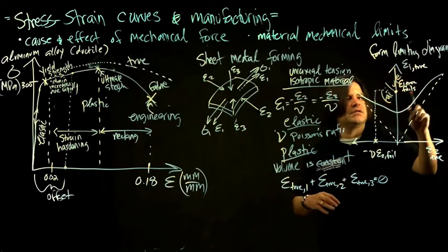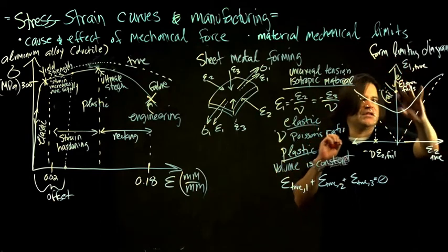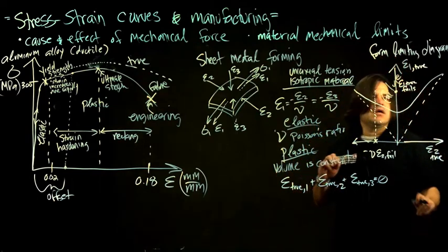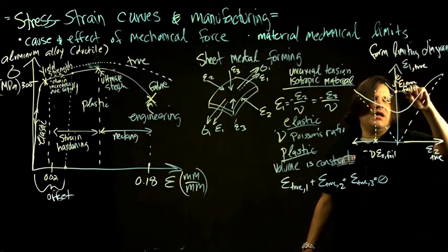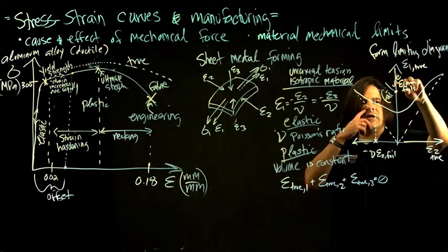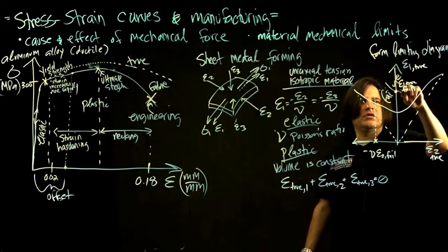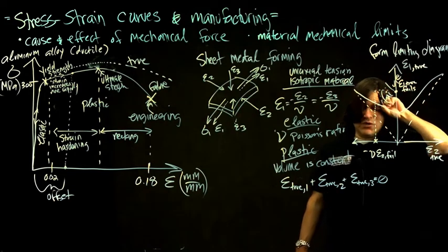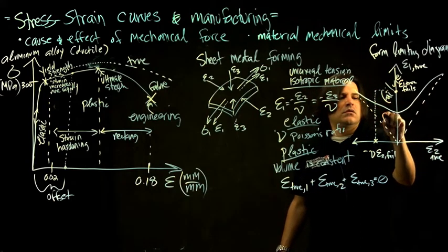You don't want this. I mean, you can't apply this high amount of stress in this direction or this direction. And what's interesting is that if you go to this high strain in this region and this amount of strain in this region, it'll survive better than it did if there was only this one direction. So that's one common feature. And then anything in here is formable.